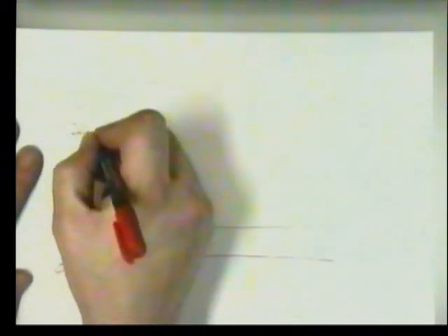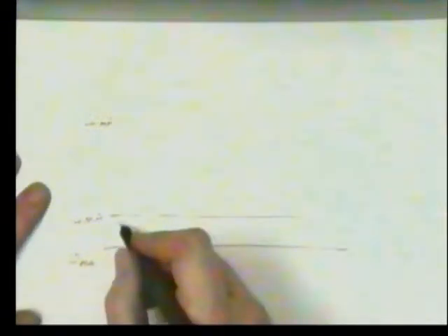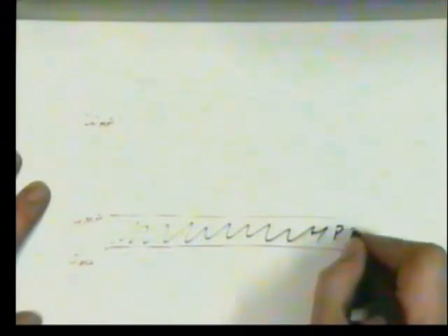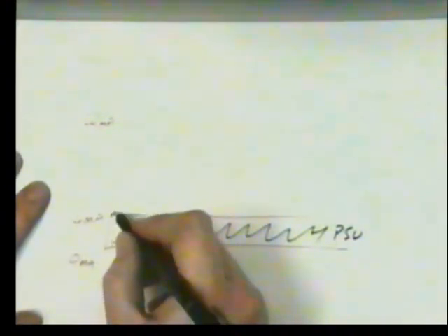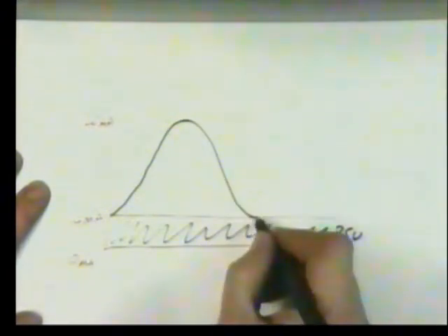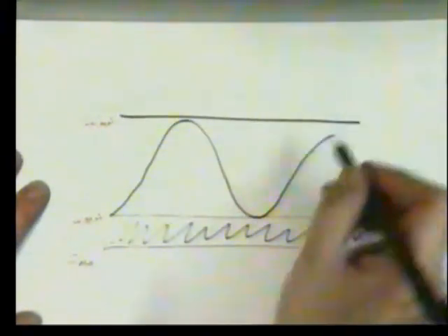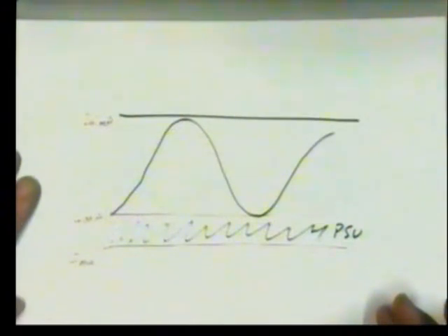So what I have introduced to you, if we just draw a graph of what happens in real time, is what is known as the 4 to 20 milliamp transmitter. There is always 4 milliamps drawn from the remote battery to power the remote system. But the actual signal we want to transmit back is achieved by modulating that information in the remaining area, the 4 to 20 milliamp band on the transmission system.